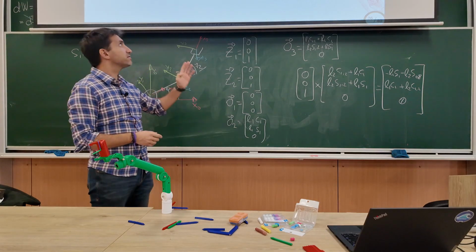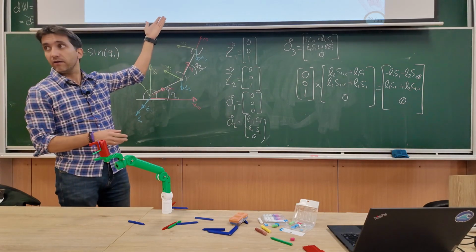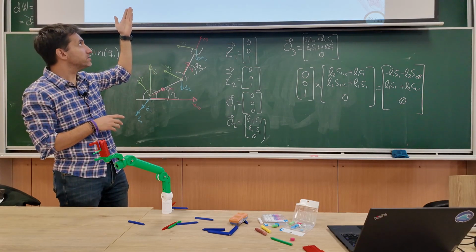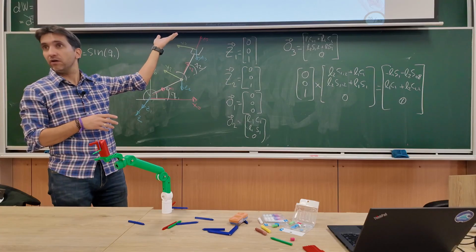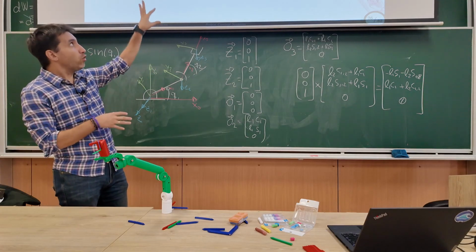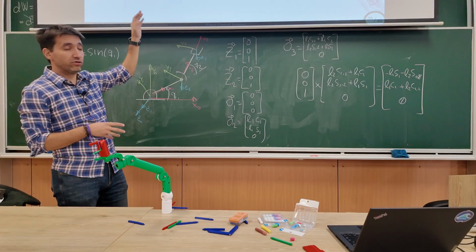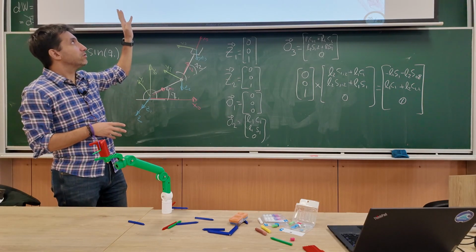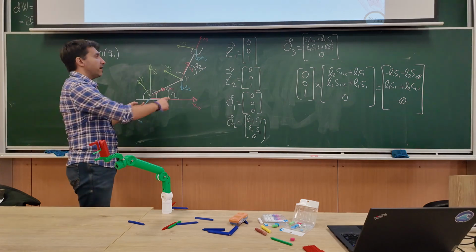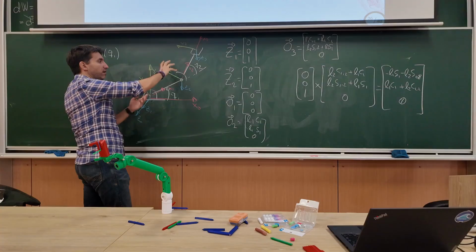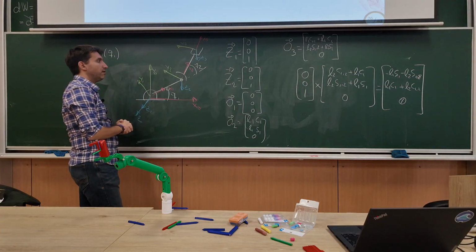All right. So that's what we see also in the equation in the matrix form. The Jacobian is a function of joint positions, joint coordinates, not velocities. Right. Not all parts of the Jacobian, you see that the angular part for this robot is not affected by the joint coordinates.